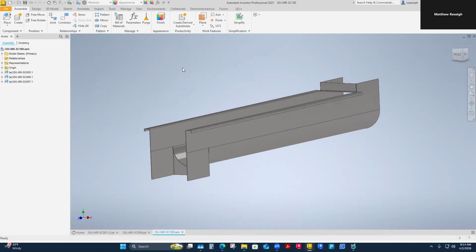If you remember right, when we exported those components, it asked if we were creating a new assembly or selecting a target assembly. Now that I've created an assembly, when I create the additional housing parts, I will be able to select this as the target assembly to send those parts to. So this will become the master housing assembly.